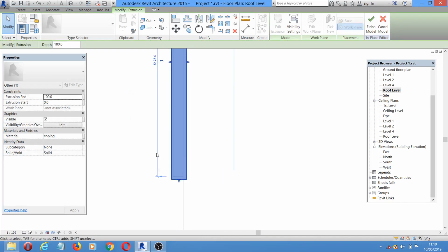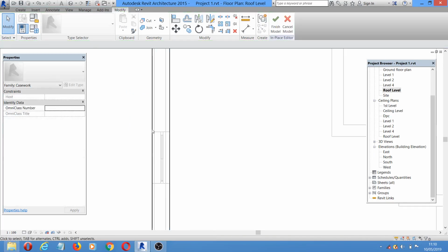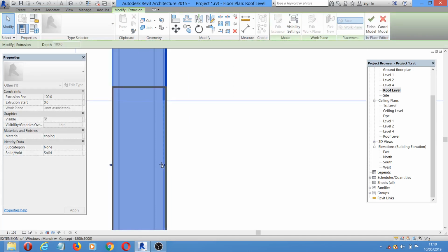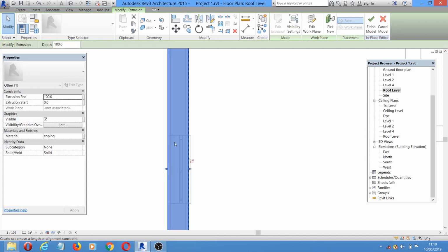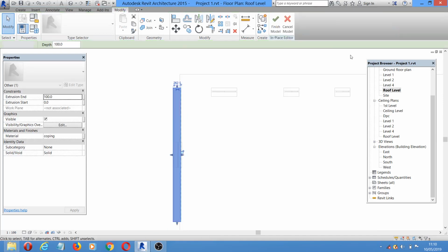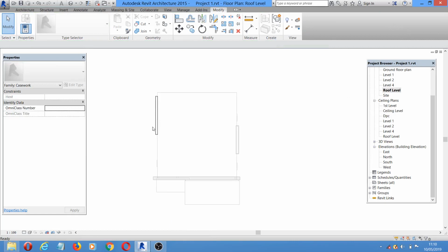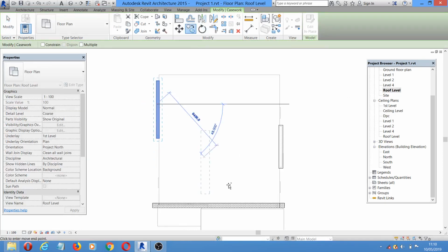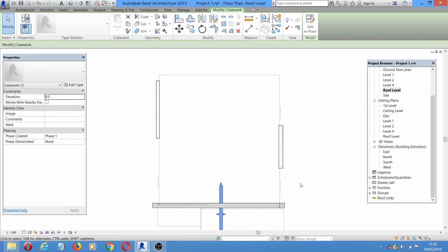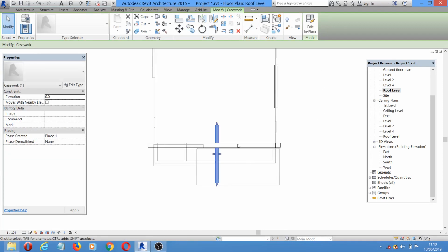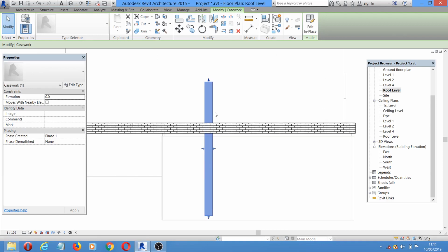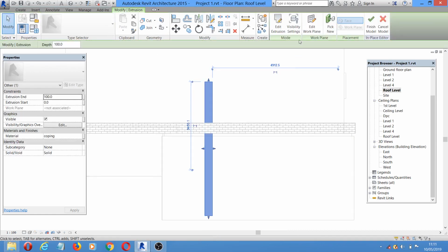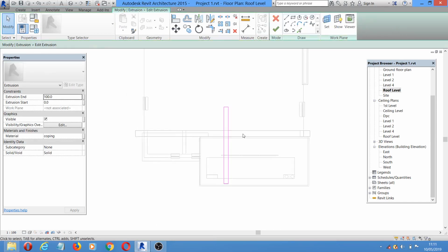Now this, you can drag it if you don't want to specify the dimension, but if you want to specify the dimension, you can use reference plane to do that, or you click on edit. So now I can still copy the same thing and do it here. Okay, assuming I want to specify the dimension, then I'm going to click on edit.